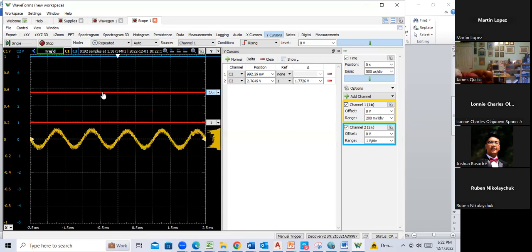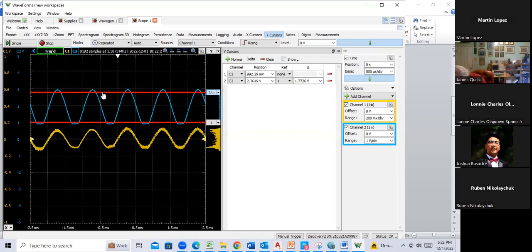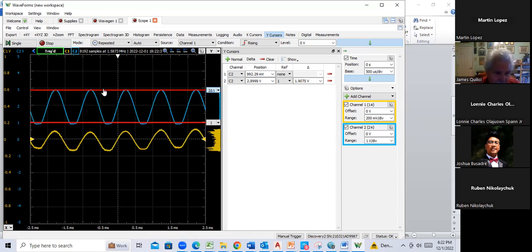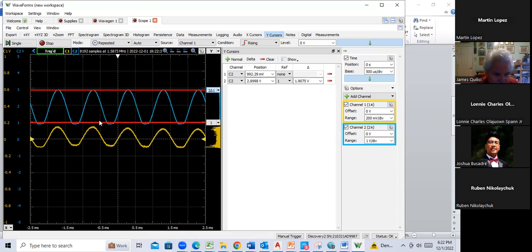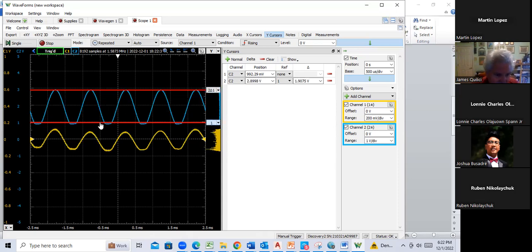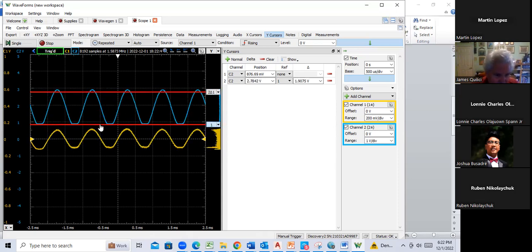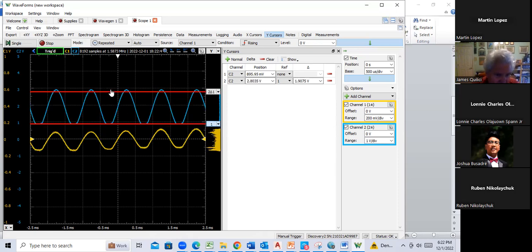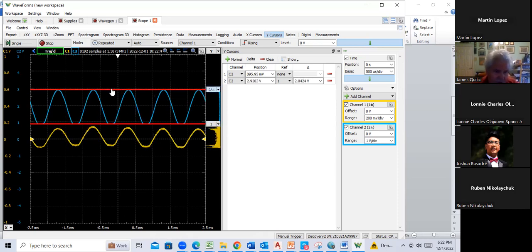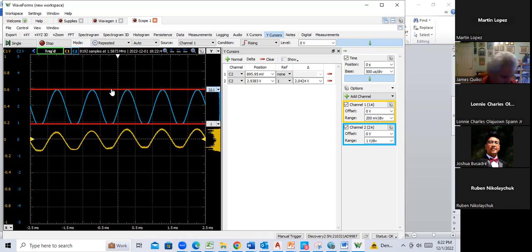I think my spec was I needed 2 volts peak to peak. Yeah, I'm running into my negative supply. So this isn't optimum. But I think I've at least got my gain. I would have to tweak around with it some more to see if I can raise the collector voltage up. Yeah, I've got 2 volts divided by 0.2. So I do have my gain.